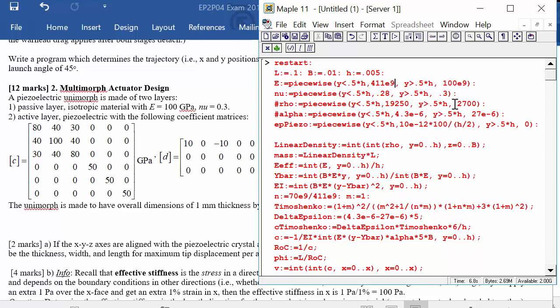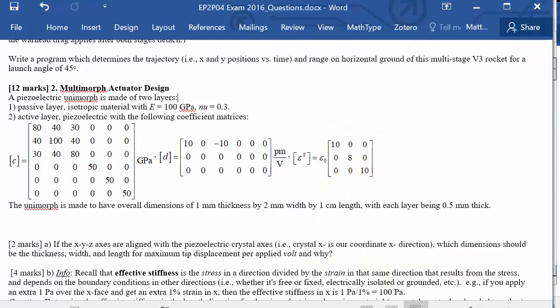The piezoelectric material is a little bit more complicated, right? So this is only the stiffness if the other directions are fixed to have zero strain. But in a beam, it's probably closer to say that the other directions have zero stress. So what we need is the inverse of the S3 component, the Z1, the length, the axial elasticity in the direction we're bending.